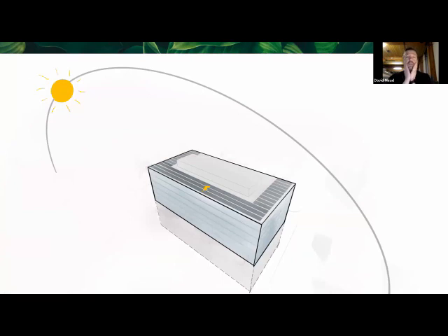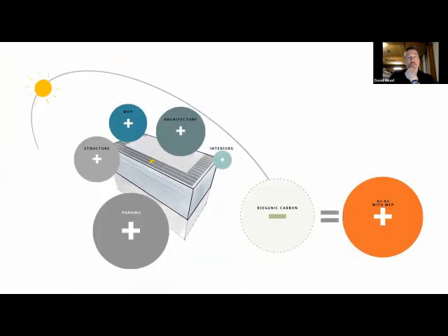So the next one, this is projects up in the Seattle area that we've been working on. Here, it was interesting. We were looking at, once again, a wood construction option. And this is looking at the positive emissions into the atmosphere. The negatives look at sequestration, and this is the balance. The wild thing here is the below grade parking garage on this development was the largest source of emissions. And there's been some research on this recently. Some others have been showing just how high that is.